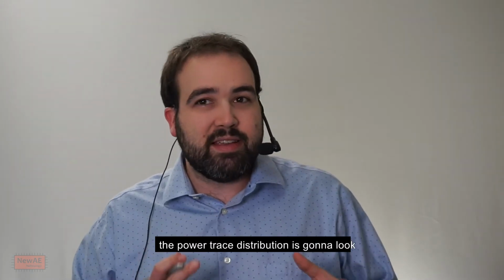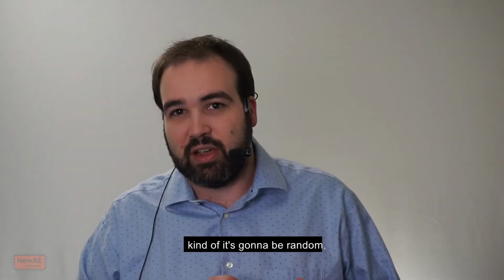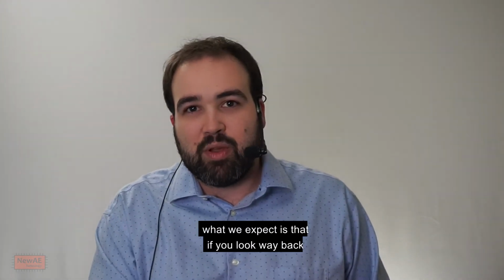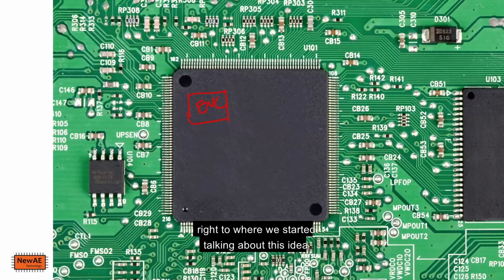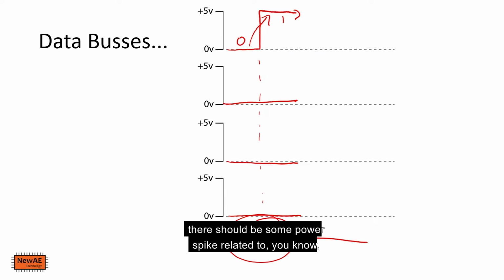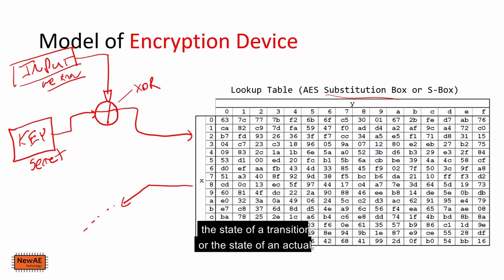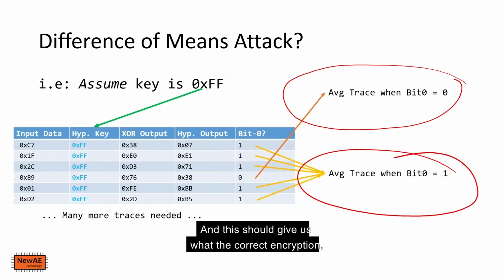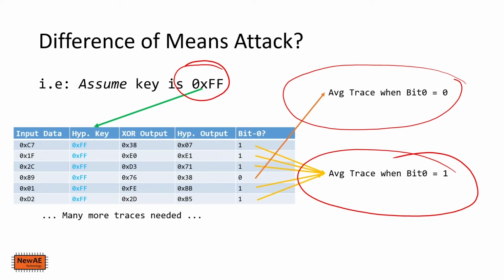If it's incorrect, the idea is that the power trace distribution is going to look random, so we'll see no big spike. If we were correct, what we expect is that if you look way back to where we started talking about this idea that there's going to be a big power spike, we're basically going to exploit that. We're going to exploit the idea there should be some power spike related to the state of a transition or, in this case, the value of the bit on the data bus itself. And this should give us what the correct encryption byte is, or the most likely byte for the key.